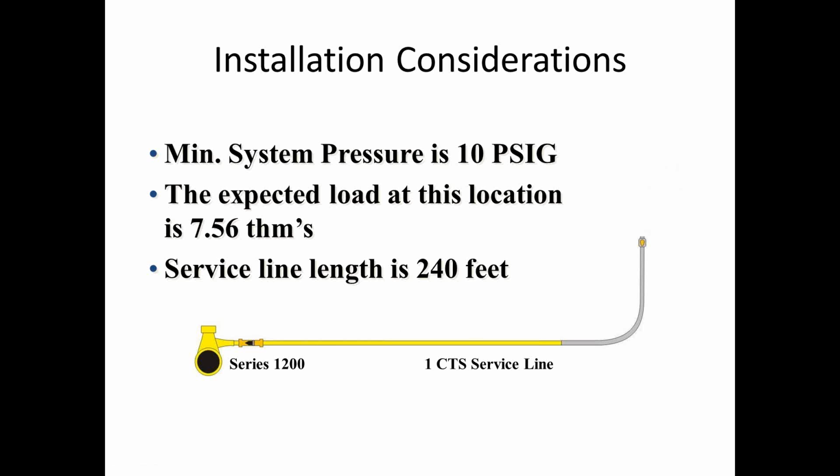What we were seeing is oftentimes crews would get into a loop where it would trip, and then they would feel the valve was not functioning correctly because it wouldn't reset, or it wouldn't allow the flow of gas. Ultimately they would want to dig out the excess flow valve, thinking that it wasn't operating correctly when actually it was doing exactly what it was designed to do, and that is closing when it was open to atmosphere. So some companies have done things like putting restrictors on the end of the valve, an orifice or something to restrict the flow before they do their bleed off, so they could open the valve all the way and it still won't trip the excess flow valve. So those are some things to consider.